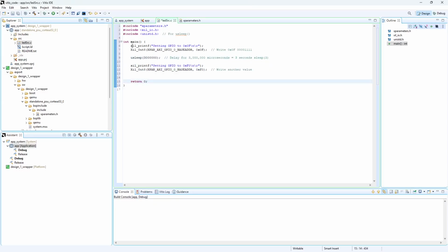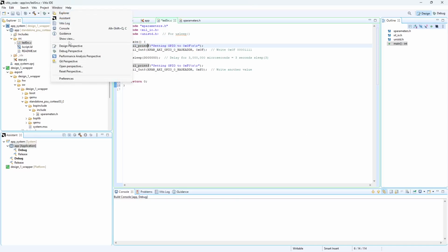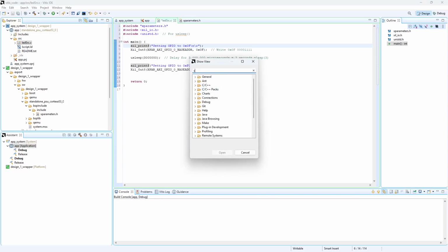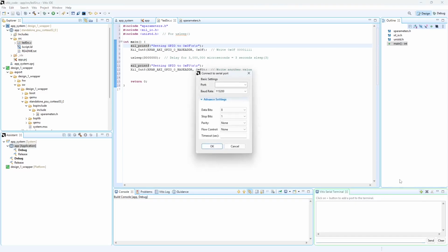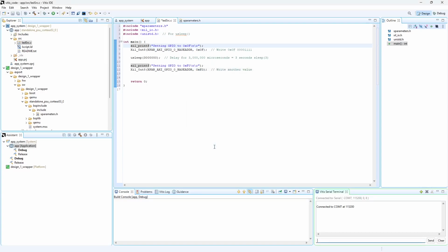And this is just for troubleshooting purposes, to check whether it's working properly. I'm just printing it with printf, so I'm printing in the serial monitor. Let me open the serial monitor also. In the Show View, type serial monitor and the serial terminal will come there. I'm keeping my board powered on. Here in the serial terminal, my board is connected to COM7. You can identify it from the Device Manager. This is the port where your UART wire is connected, UART, not the JTAG. Because this communication will be from the board through UART, you are seeing it in the terminal.